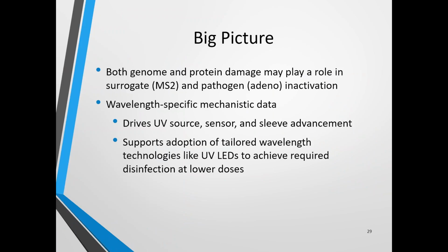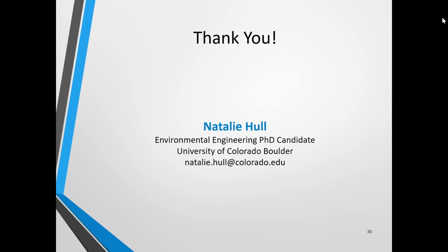Just to summarize the big picture for this, both genome and protein damage may play a role in inactivation of both of these viruses, MS2 and adenovirus. And we can use these wavelength-specific data to drive UV source, sensor, and sleeve technology advancements. And these data and the implementation studies can support adoption of tailored wavelength technologies like UV LEDs to help small systems and just in general achieve required disinfection but using lower overall doses. Thank you.